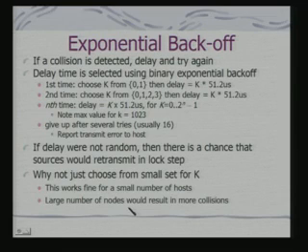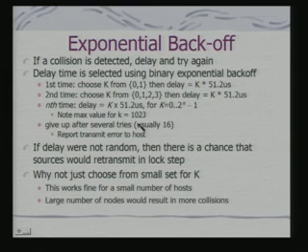Now, what is important to note as an embedded system designer is that because of this random wait parameter getting involved, the performance of Ethernet is not completely predictable. If I want to have any real time service supported on Ethernet, I would like to have predictable performance. Because of this exponential back off with a random selection of delay, the performance of Ethernet is not strictly predictable.